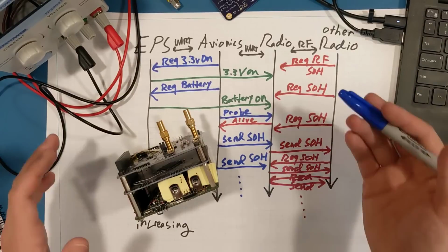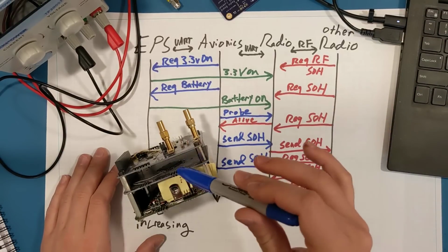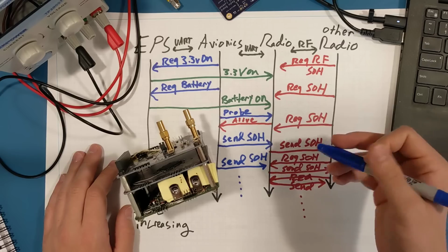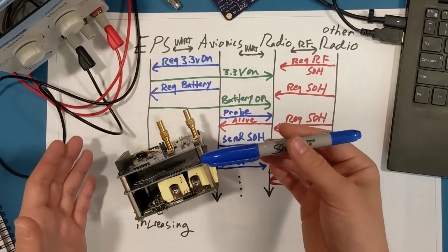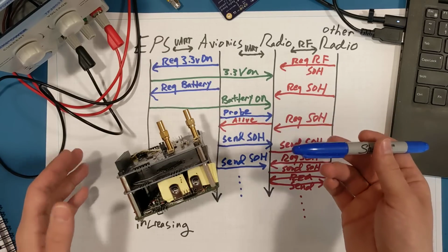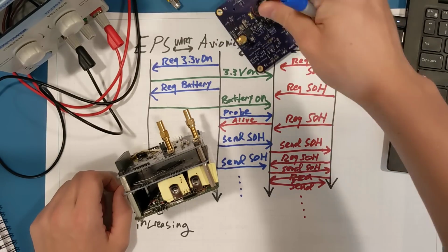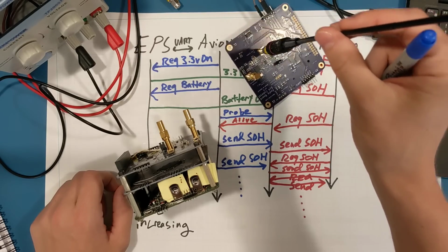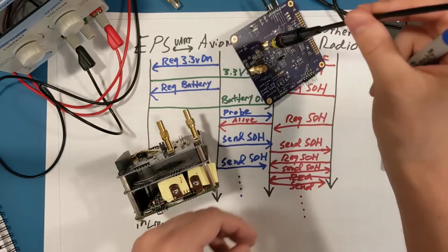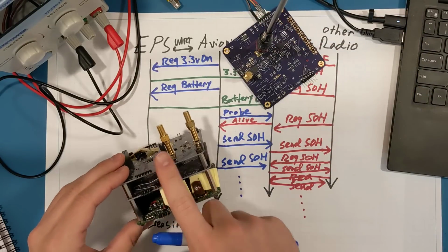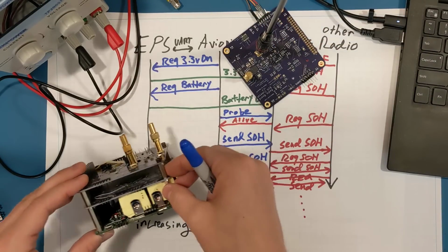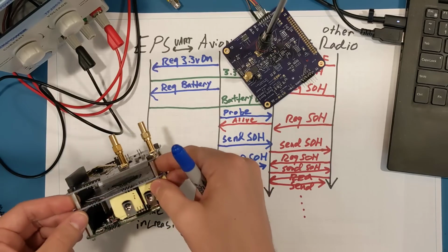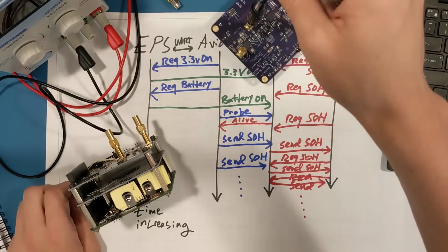I did it this way such that this radio does not just continually transmit and burn a whole bunch of power, and that way I can control just when it is actively transmitting, since presumably I would control when I am using this radio, which is connected to my computer. So if I transmit from this guy, only then will the CubeSat respond. In practice, I could change this such that the CubeSat is more talkative, but that's just a configuration.